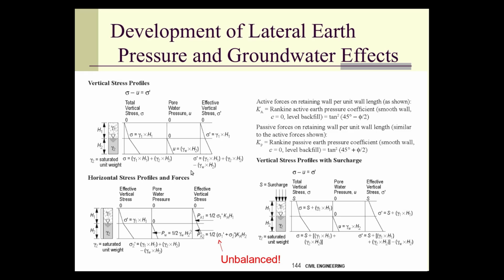Now, the horizontal is likewise to the vertical. If the water level is the same on both sides of the wall, then we don't count this pore water pressure. That's why this is only counted if it's an unbalanced force. The effective vertical stress is over here.